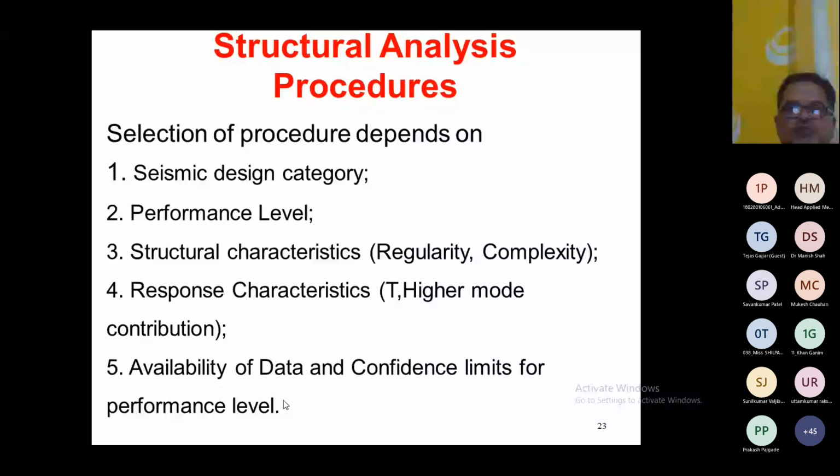So how can you select this procedure? It depends on the seismic design category, right? Now, which type of structure you are designing, right? If you are designing a very important structure, then definitely you have to go for the dynamic analysis. Performance level means we have different performance levels. We have life safety, immediate occupancy, collapse prevention, many different types of performance we are defining, and on that basis also we select these methods.